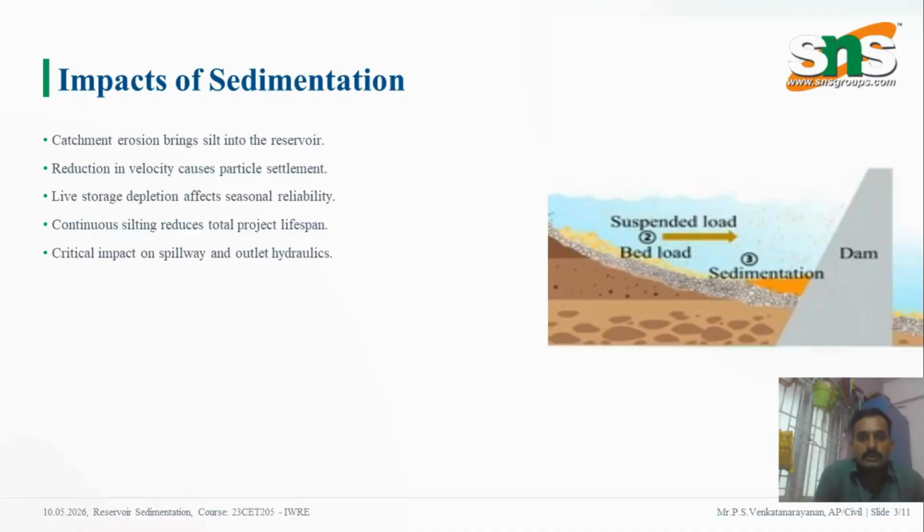Another serious issue is the impact on spillways and outlet hydraulics, which may become less efficient due to sediment accumulation. Therefore, sedimentation management is an important part of reservoir planning and operation. Without proper control measures, even a well-designed reservoir can lose its usefulness much earlier than its expected lifespan.